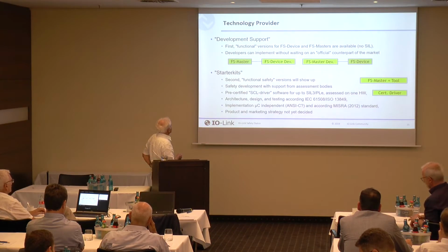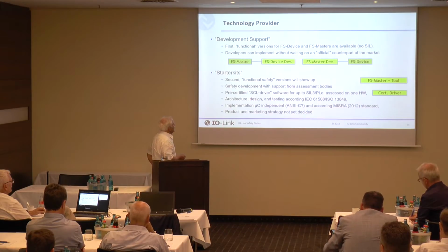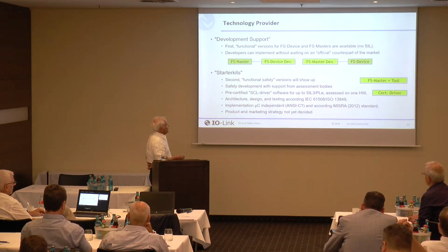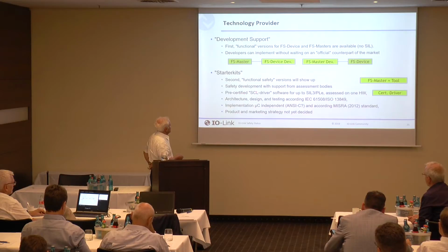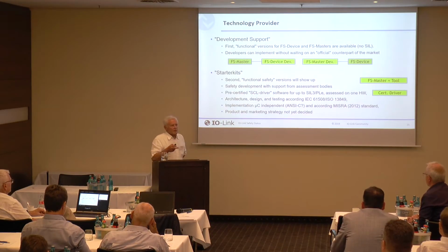And in the next step, we intend to provide starter kits, and these will be functional safety versions. With safety development, with support from assessment bodies such as TÜV Süd, we will create pre-certified SCL drivers. SCL is safety communication layer, the protocol driver software for up to CL3 and PLE, assessed on one hardware.